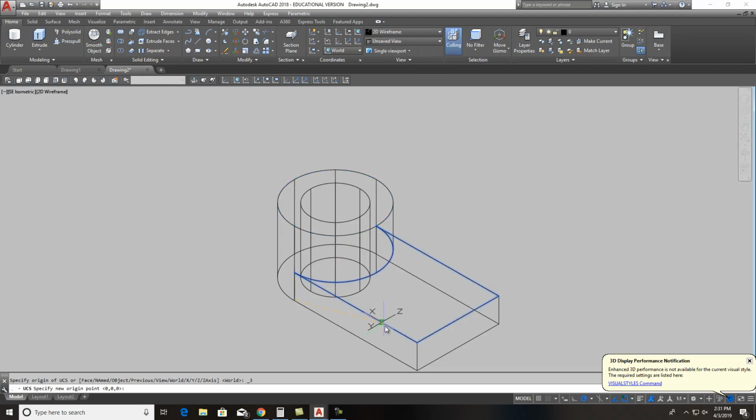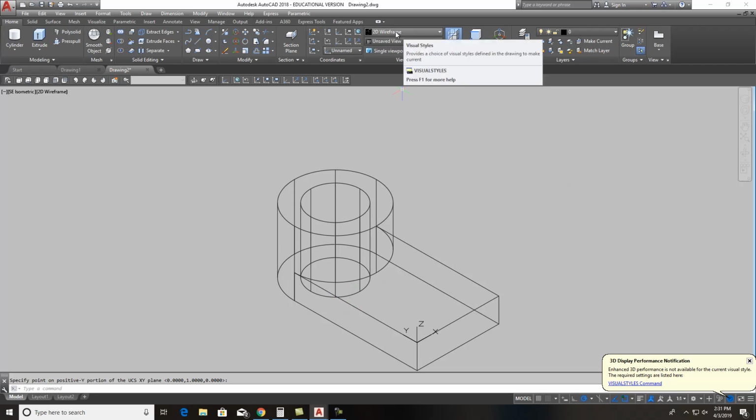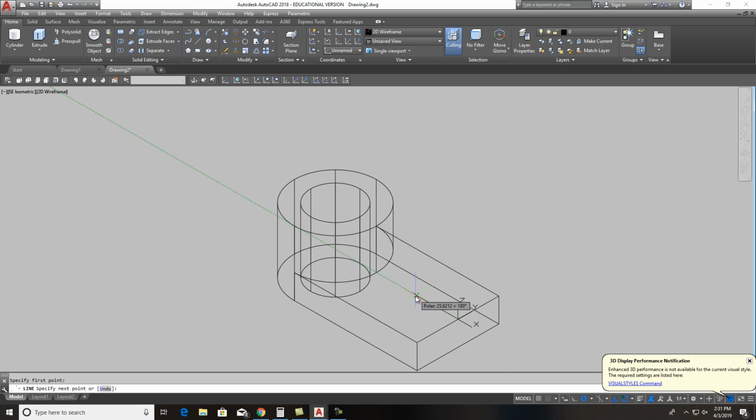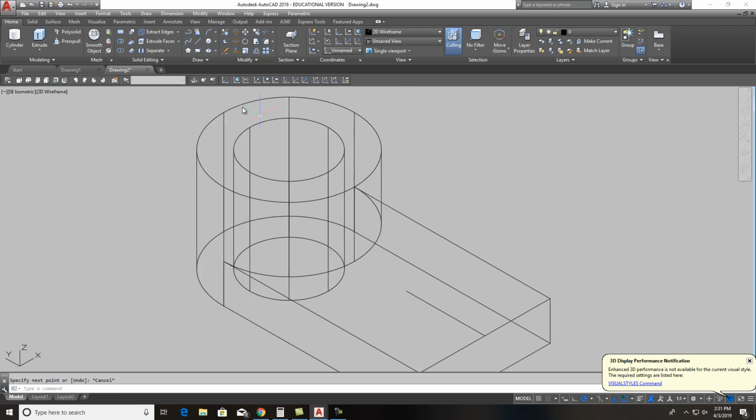If it gets to the point it's been difficult on us, we'll hit this point and get on that line. You see what I mean? If you can't get it to snap or do something, sometimes you're better off going to a 2D wireframe. So now, right in the center of this thing, I catch that midpoint, and I want to come back exactly from that edge. X minus 30. So I'm going to come back 30, and right there is going to be the end point where the circle is going to be.